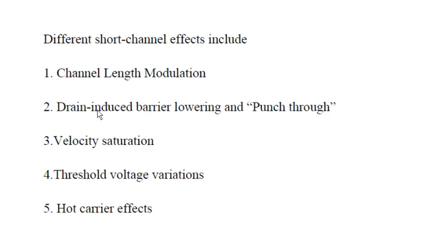And we have different short channel effects, including channel length modulation, drain induced barrier lowering and punch through, velocity saturation, threshold voltage variation, and hot carrier effect. We have different short channel effects or secondary effects due to the shortening of the MOSFET channel. The important ones are channel length modulation, drain induced barrier lowering, velocity saturation, threshold voltage variation, and hot carrier effect. These are all known as short channel effects. We will see them one by one.